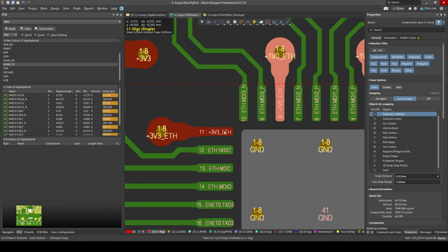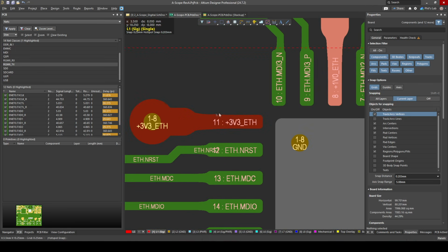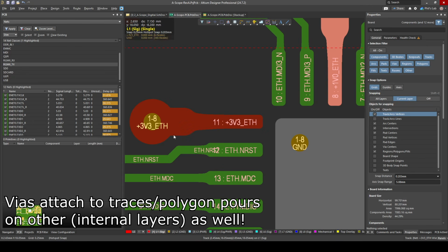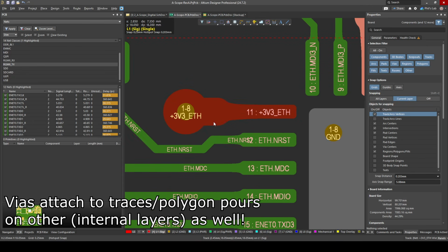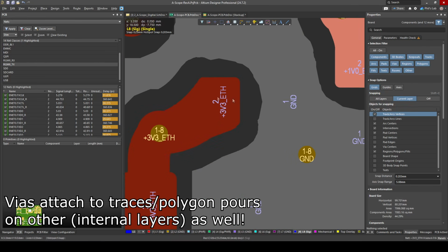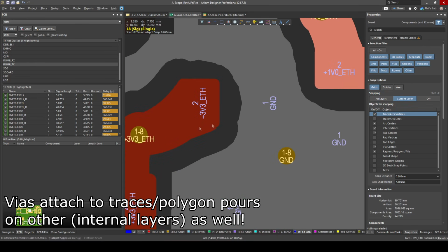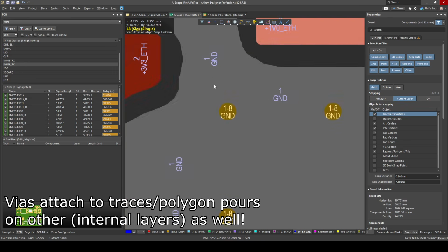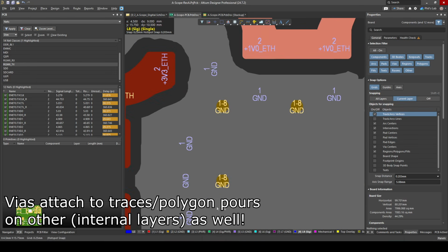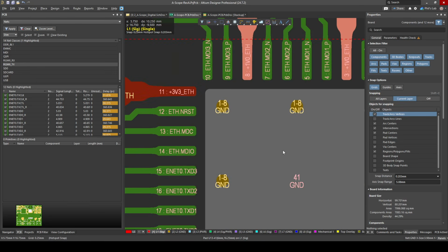And anytime I have a power pad on the outside perimeter, I neck down into the width of that pad, place a via as close as I can, given the other signals that need to route out and into this package, place my decoupling capacitor on the bottom side, connect with a short wide trace, and then a ground flood that connects to the grounding vias that can go back up into the QFN package.